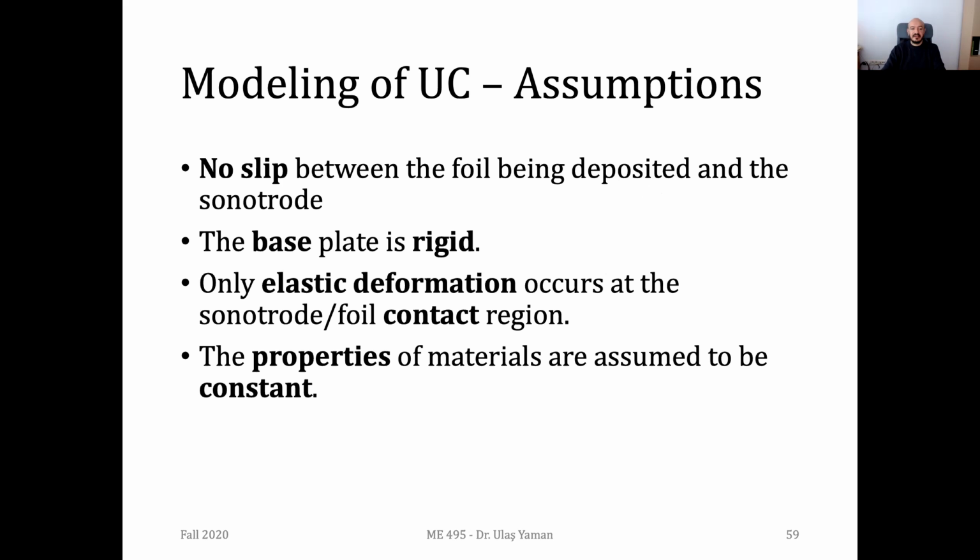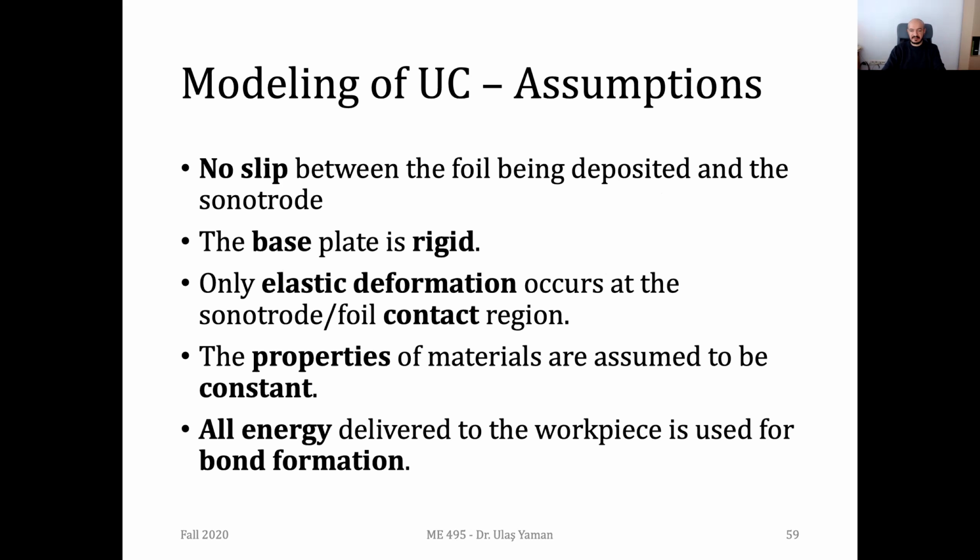Another assumption, the mechanical properties of all these materials are not changed during this process. We are assuming that they are all constant. Another assumption: the ultrasonic energy, which is generated with the help of the vibration and the amplitude of the vibration, is totally transferred to the bond formation. So we are not using this energy elsewhere in our system. It's just used for joining the sheet metals together.